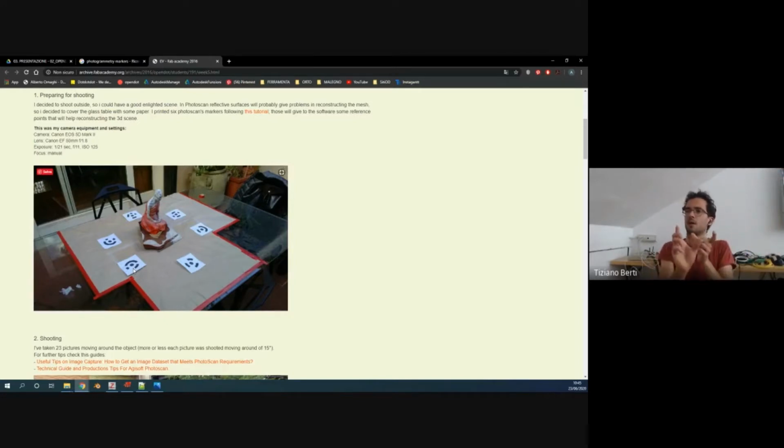In the part where you are going from one room to the other, you usually put a lot of markers, because it's the point where it's most difficult to align the two scans together. So you are using those markers to put different data sets together. You're maybe getting a point cloud of the room, then another point cloud of the other room, and then you're using these markers to align the two 3D scans together.